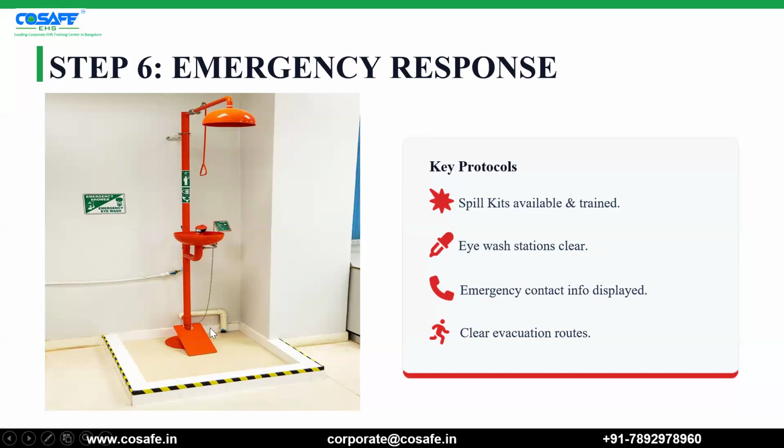Because these eye washers and showers are kept there for a long time and are not used frequently in many companies, the pipes corrode from inside, and the water gets contaminated when it is released from the shower or the eye washer. This can cause other harm to the health of employees or workers. Am I clear? You have to maintain this in very good condition.